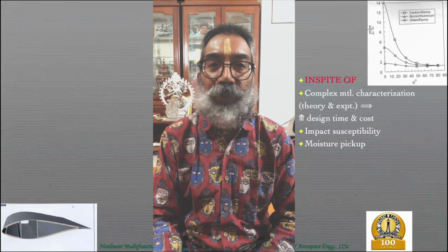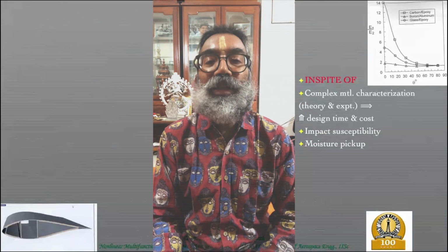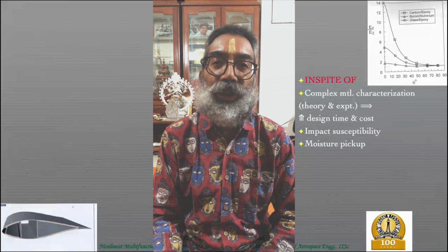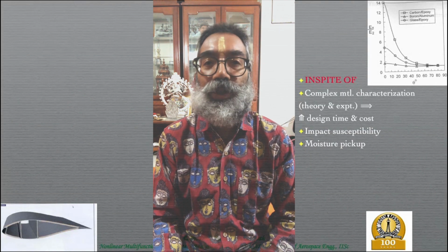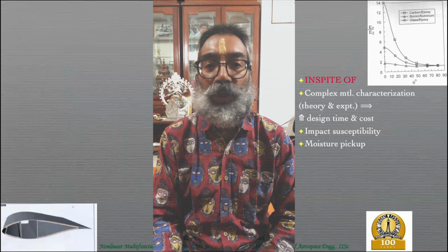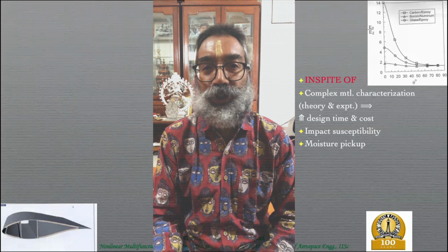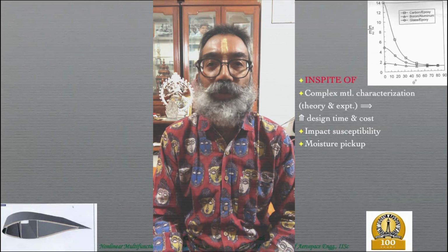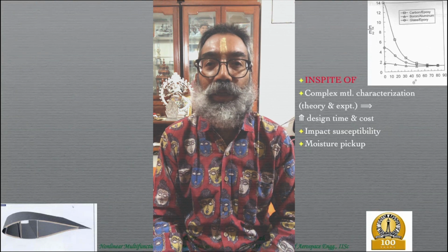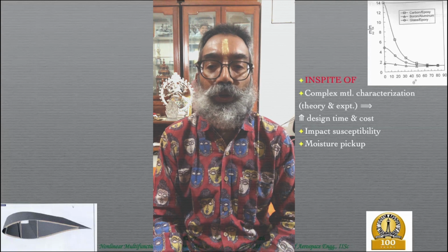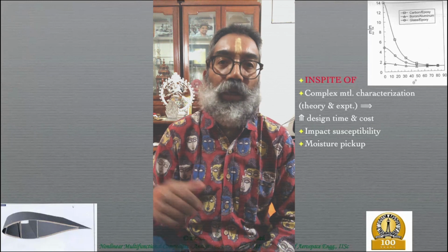And these moisture pickups by polymers, certain polymers more than the other polymers, can result in certain swelling, because of which there's a dimensional change, but more importantly, there is also a reduction in the performance in terms of some of the mechanical properties getting degraded because of the moisture absorption. So that's something that is of concern, and there are many different design changes that are done in order to accomplish that. We will look at some of them, time permitting, when we go a little more into detail on